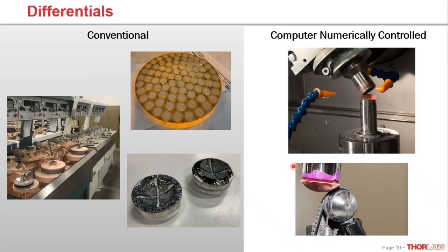And then additionally, showing an added feature that we have, the ability to then take our optics into a magnetorheological finishing setup. Here we see the workpiece fixtured and being passed through this ferrous fluid, for which we know the defined signature of removal for the part. And here we can use subaperture removal techniques to improve the finishes even further beyond a standard polished part.